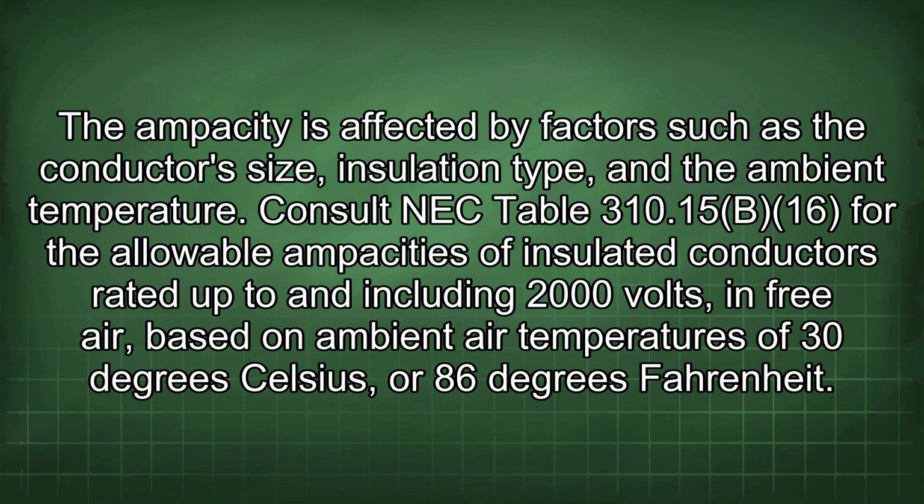Consult NEC Table 310.15(B)(16) for the allowable ampacities of insulated conductors rated up to and including 2000 volts, in free air, based on ambient air temperatures of 30 degrees Celsius or 86 degrees Fahrenheit.